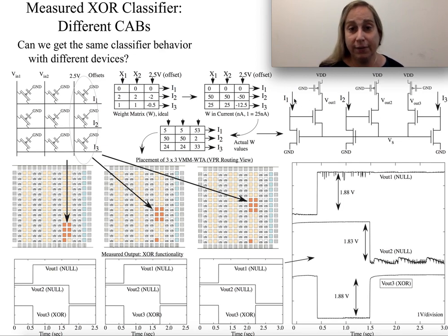And therefore I have these inputs, and I effectively have these outputs, which are now voltage outputs, and I actually have floating gates sitting here to set those. Those also show up in the routing fabric. Now, I could have put a lot of this into one CAB, easy enough to do this in a couple CABs and then just route as needed, and then have a single current source, which I believe is what was put in these single points at the bottom.